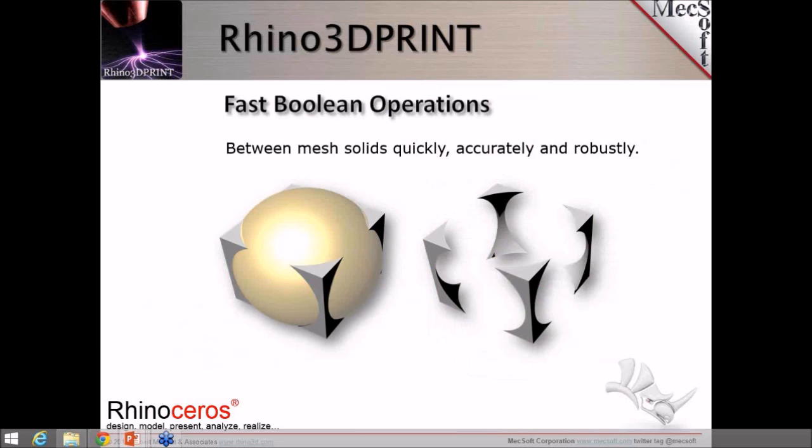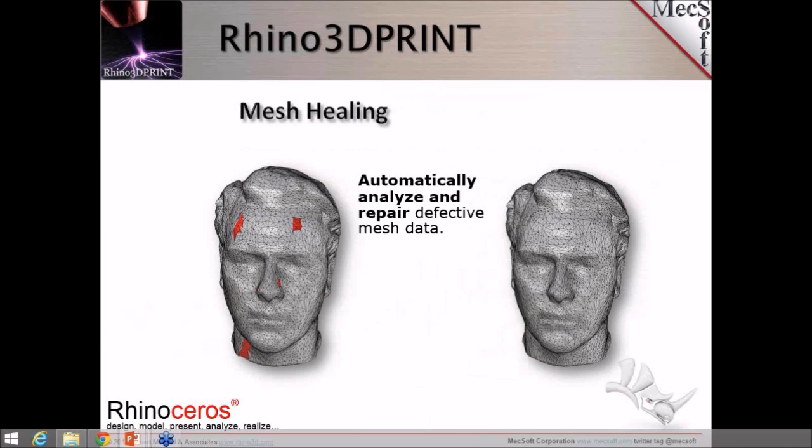Rhino3DPRINT performs mesh booleans, union, subtraction, and intersection, that may be too complex for Rhino's built-in mesh boolean commands. Rhino3DPRINT auto-fixes meshes to remove gaps, holes, and self-intersections. It is not unusual to have 20,000 to 40,000 holes or openings in one imported model. This would take hours to fix in Rhino manually. Also, Rhino3DPRINT highlights the Rhino model and shows in color the areas that are bad.